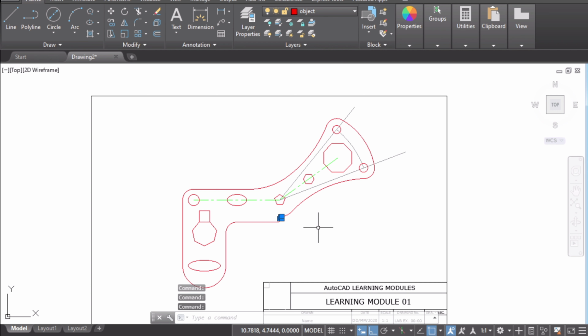In case you want to connect all this border as a single geometry, we can use the Polyline command or p-edit in AutoCAD. So the polyline stands for the combination of straight lines and curves together and acts like a single geometry.